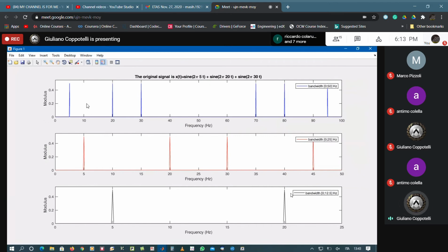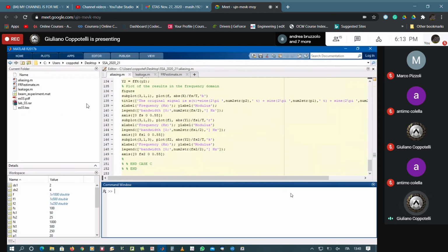We can't have any other information with respect to the true signal properties because of the sampling frequency. But what we got in that frequency range is the good one. There is no aliasing, there is no mirroring that could be leading us to a wrong identification. Okay, so that is very interesting from the aliasing point of view.